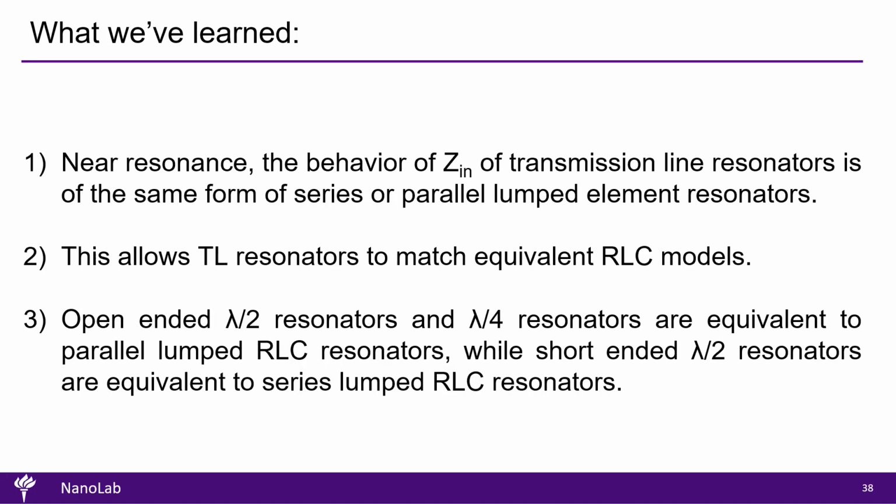Let's quickly review what we learned in this Lightspeed session. First, near resonance, the behavior of Zin for transmission line resonators follows the same pattern as series or parallel lumped element resonators. Second, this means we can match transmission line resonators to equivalent RLC models. And third, open-ended half-wavelength resonators and quarter-wavelength resonators behave like parallel lumped RLC resonators, while short-ended half-wavelength resonators behave like series lumped RLC resonators.